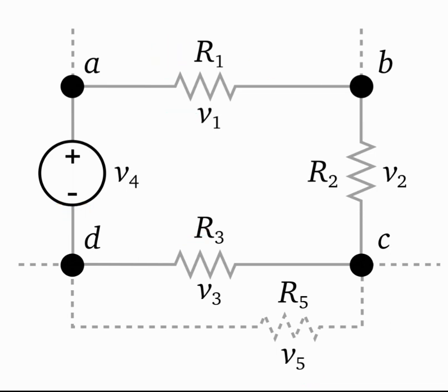all of these resistors. Since the resistors R3 and R5 are connected in parallel, because you see the two ends of both the resistors are connected at the same nodes or same junctions, therefore they are in parallel, and therefore the voltage drop across each of them is the same. In other words, V3 and V5 would be the same. Okay, but our focus in this module is to explain what is KVL, Kirchhoff's voltage